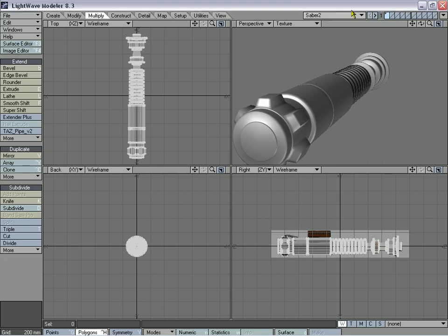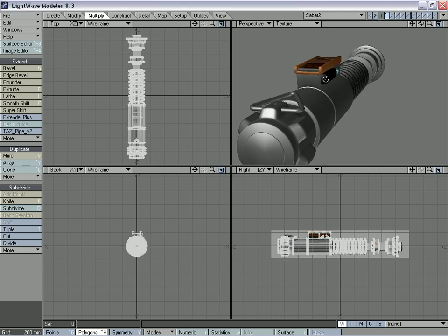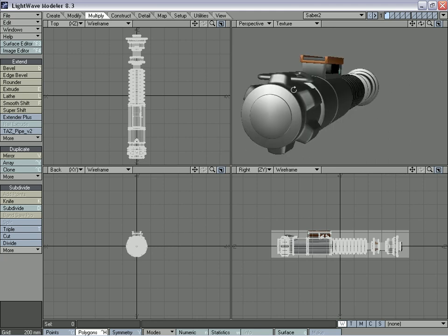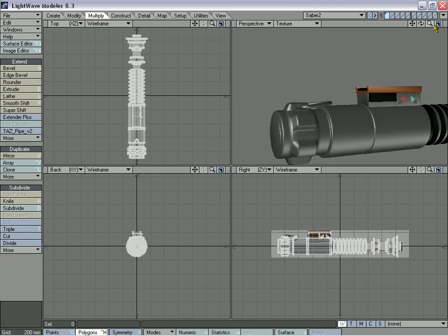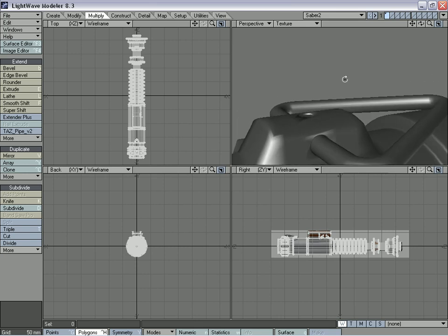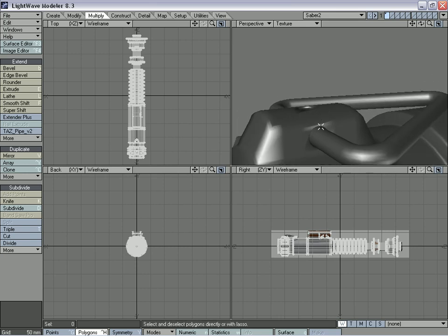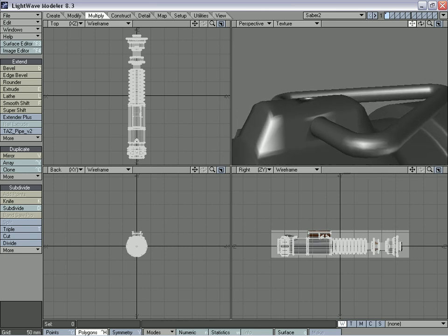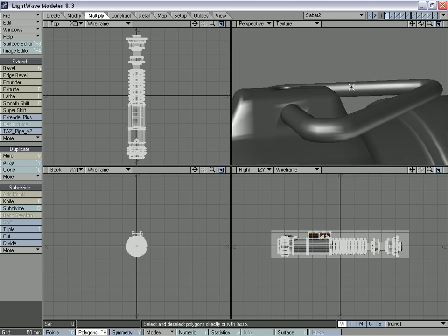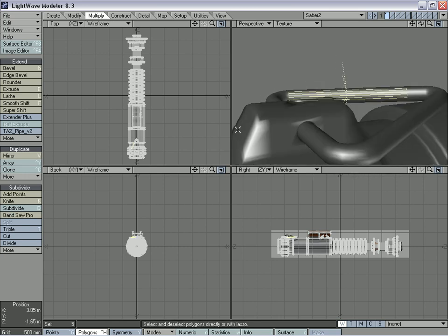If you notice, on the main model here we have a sort of belt clip ring on here. And for that, we're going to need to create... See, if you notice here we created a hole, but it's added a lot of distortion. And actually what we can do is just take this and model this ring, this little clip, and just make it go directly through.